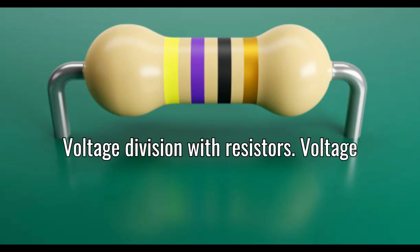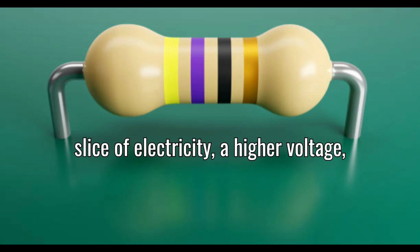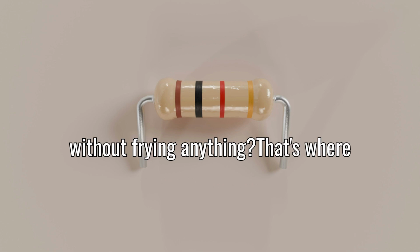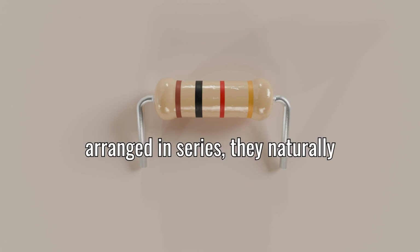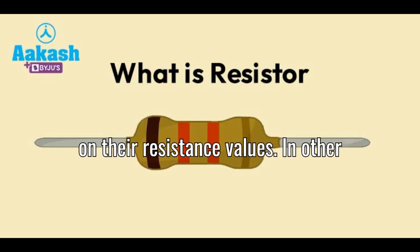Voltage division with resistors. Voltage division is another clever role resistors play in circuits. Imagine you have a big slice of electricity, a higher voltage, but one part of your circuit only needs a smaller slice. How do you split it up without frying anything? That's where resistors come in. When resistors are arranged in series, they naturally share or divide the voltage between them. The ratio of this sharing depends on their resistance values.